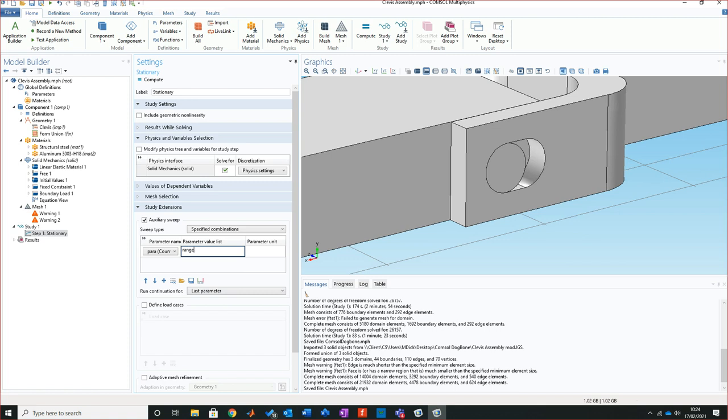It's going to go range. I'm going to use the same parameters, 0.025, and then offer it in multiples of 0.025, and then I want it to run to the value of 1. So that's just the multiples of the pressure output. And that is done. Again, just going to hit save.